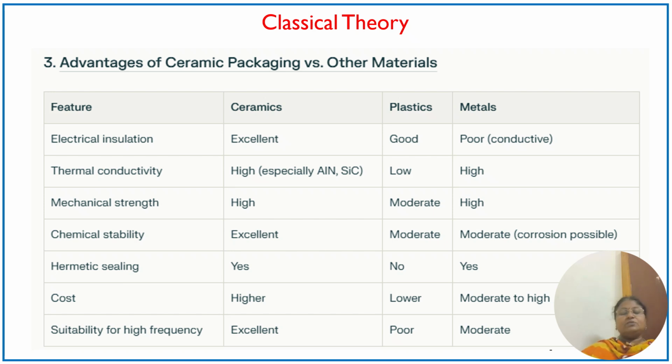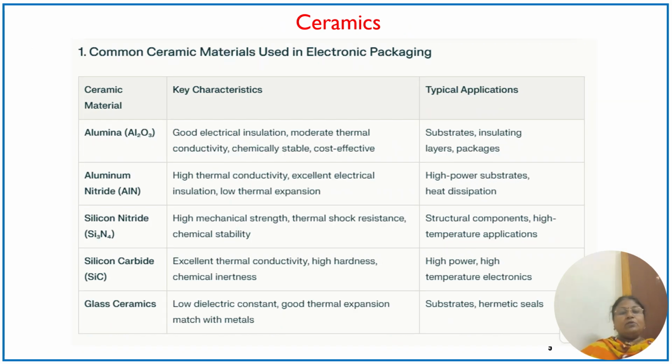So ceramic plays a vital role in today's life. Low temperature and high temperature profiles, that is your HTCC and LTCC components, are used in almost all our designs. And in terms of electronic packaging, alumina will be a very good material which is going to be used for substrates, and aluminium nitride is used for high thermal conductivity, thermocouples, temperature sensors.